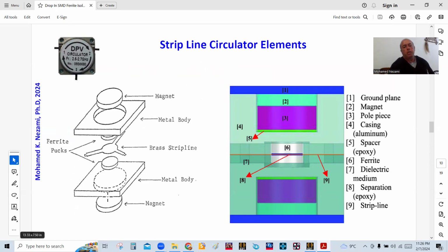So basically, you still have, just like the microstrip ferrite isolator that we went through in the last videos, which I urge you to watch before you watch this, a Y junction, which is made of a disc with 3 transmission lines 120 degrees apart, that are suspended in air basically. And then we have 2 ferrite cores in here at a particular diameter. Same thing in here, we have a particular diameter to the disc as well.